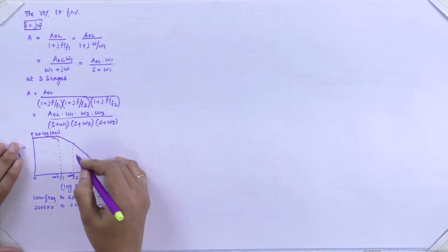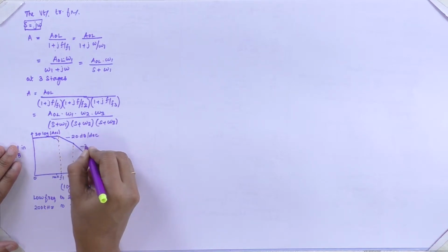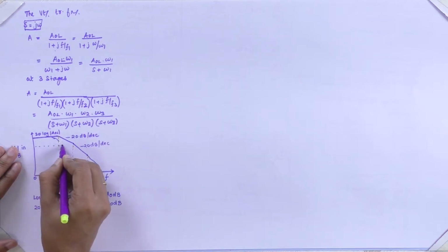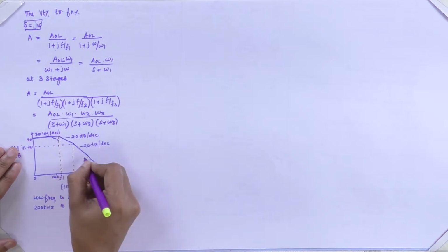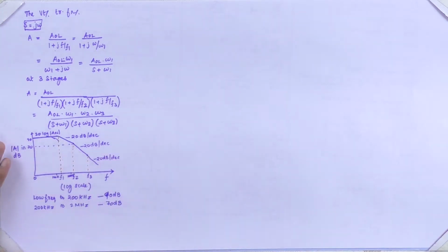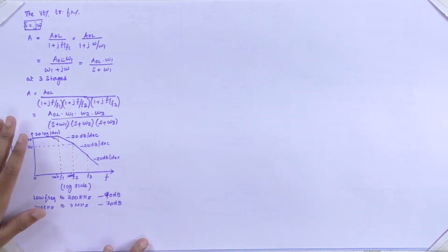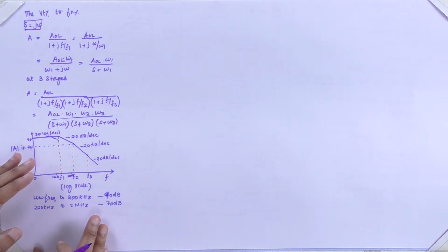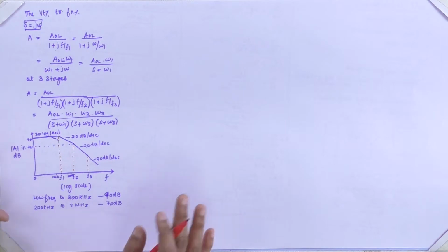Okay. So every time here we have minus 20 decibel decay rolls off. Here minus 20 decibel decay. So in this minus 20 decibel decay, it may get 90 decibels. In this condition, it may roll to 70 decibels. So again it gets minus 20. So by increasing the number of capacitive components in our op-amp circuit, every time it gets rolled off by 20 decibel. Now as frequency is increasing, the cascading effect of this RC comes into effect. So here the rolling rate increases.